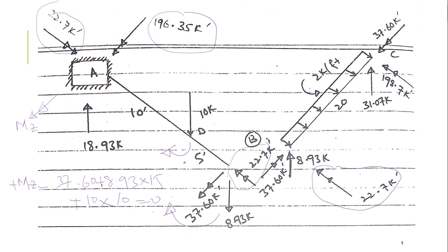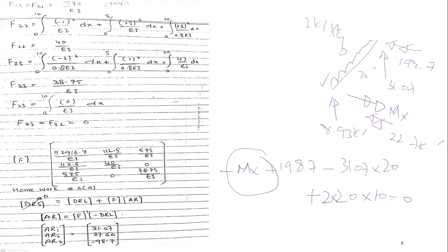I think you need a little practice, and it is the same as the concept from basic mechanics. Likewise, for example, you have a moment of 10 kip foot and you have to find a moment here. Then you balance all moments here, you find a support reaction, then you transfer moment here, you balance here with equal and opposite, and you find a moment here. I don't think this is very difficult, but you have to recall the basic concepts, and the basic concepts are very easy and simple to follow.